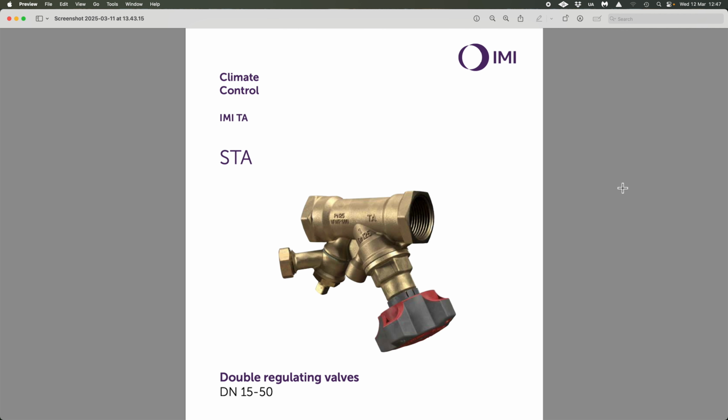So there's an error on the people that are doing the surveys, the engineers that are trying to put these systems in. And that, frankly, is just not cricket, is it? We can see that is because people are getting made ill through this. So we had to literally go in there, evaluate who was on what water system, and then drop the water levels within the stored water in order that these properties would get the throughput that they needed and the replenishment from fresh water, so we didn't have the problems of microbial growth.